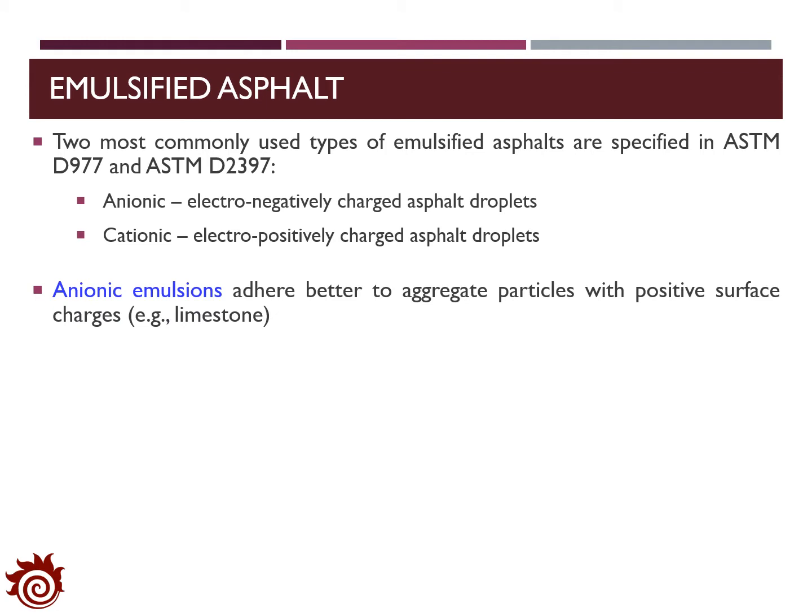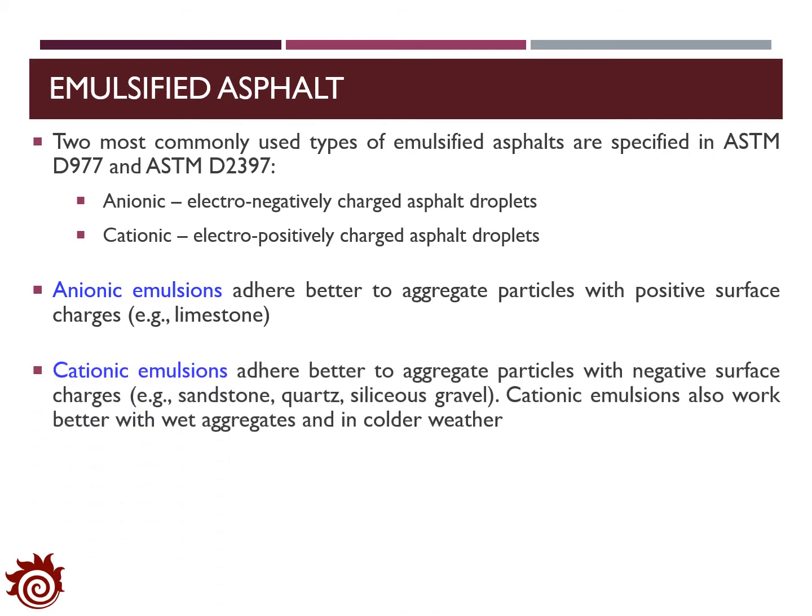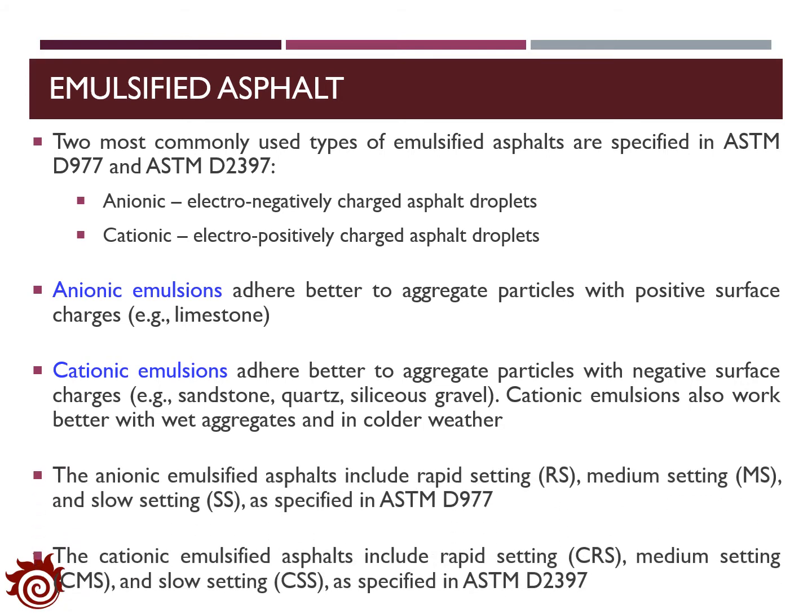Usually, the anionic emulsion can adhere better to aggregate particles with positive surface charge, such as limestone, while the cationic emulsion can adhere better to aggregate particles with negative surface charge, such as sandstone, quartz, and siliceous gravel. The cationic emulsion can also work very well with wet aggregates and cold weather. Both emulsions can have the rapid, medium, and slow settings, which are specified in the ASTM D977 and D2397 standards.